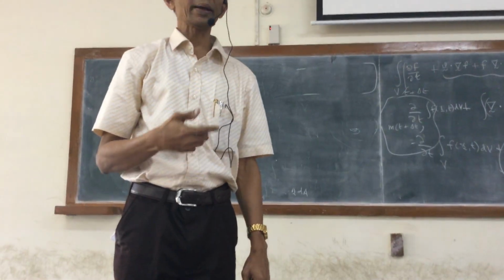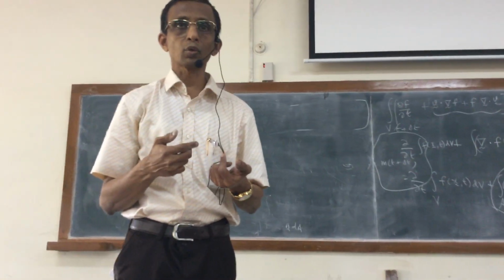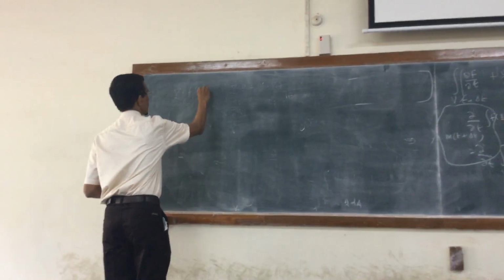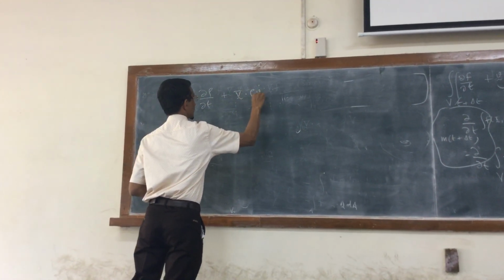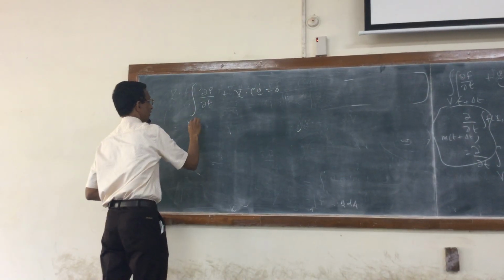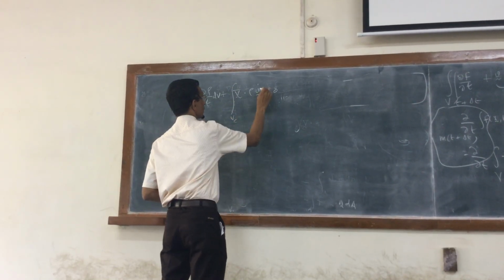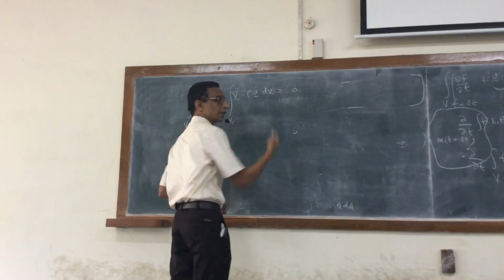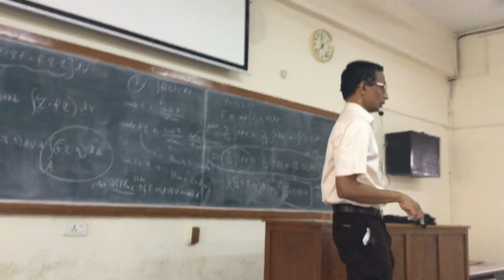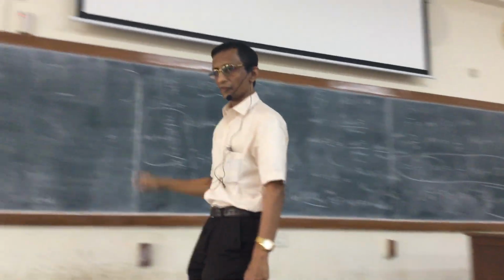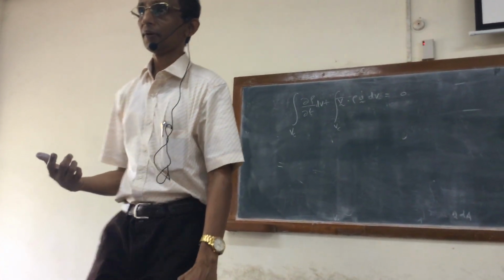So now, since I have got an equation that is valid at every point, I can integrate it over any control volume of interest. So from the local equation, I can integrate it over a fixed control volume; I'll assume the control volume is not moving, for simplicity. Equal to that will also be 0. 0 when it is integrated over any volume will be 0. So I am getting now a different kind of a global balance which is valid for a control volume for which the mass need not be conserved.